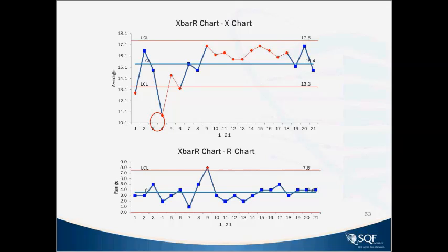Something's happened, and he knows that because the control limit from the data is what they should normally be working within. Similarly, on the range chart, this point I'm pointing to on the R chart coincides directly with the range value. So you're always plotting the X bar and the R at the same time.